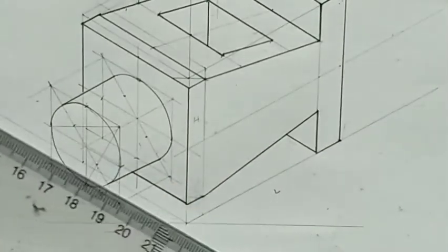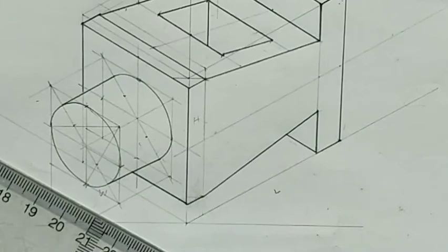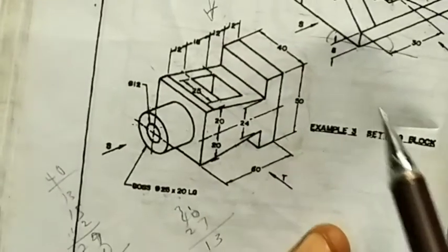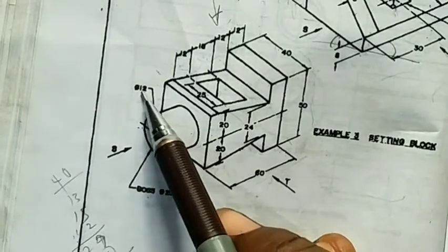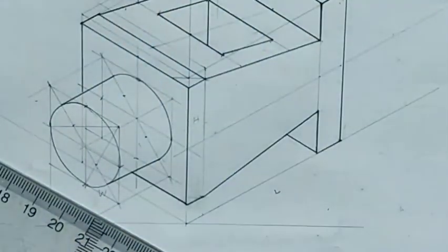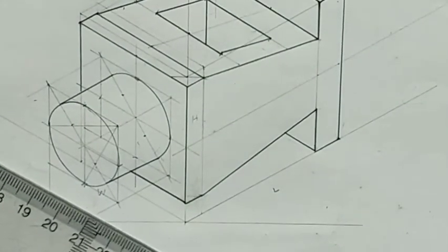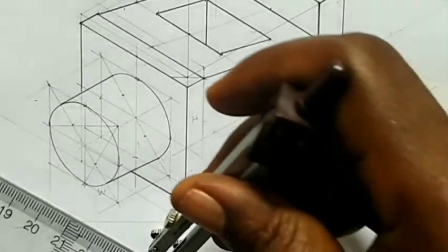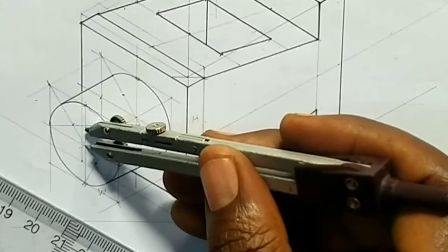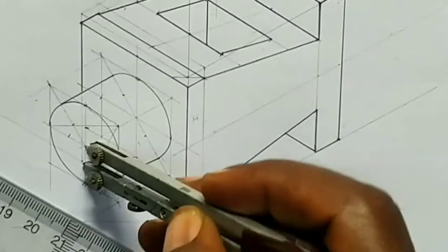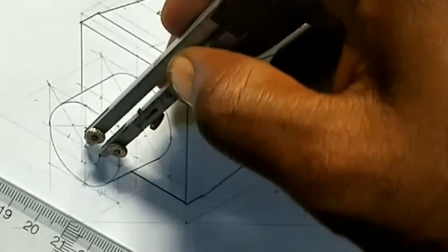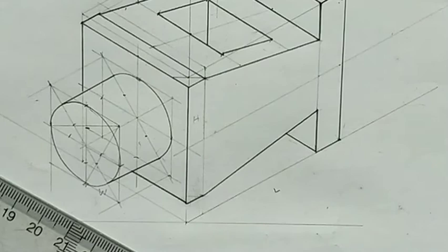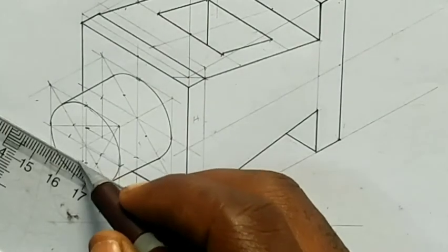don't touch here. So I need a circle inside, because if you check the question very well, there's another circle inside here, and you see it's a diameter of 12, that is 6. So since it is 12, I'll measure 12 for my diameter, and the radius, half of 12, which is 6. I'll place it at the center here where they meet. I'm going to mark 6, 6, 6, and 6 on the vertical and horizontal lines. I'll make them form a box. So this is the first box,